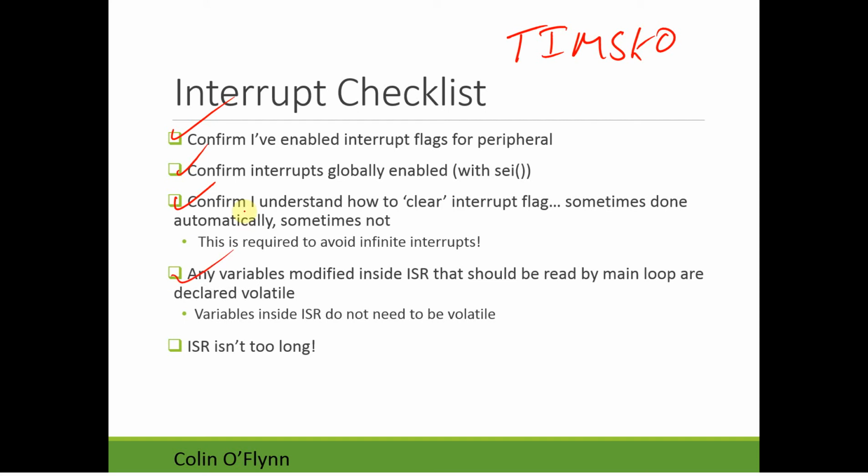You need to check that any variables you modify inside the interrupt service routine that the main loop might need to read the value of are declared volatile. As I mentioned, anything used only inside it doesn't need to be.